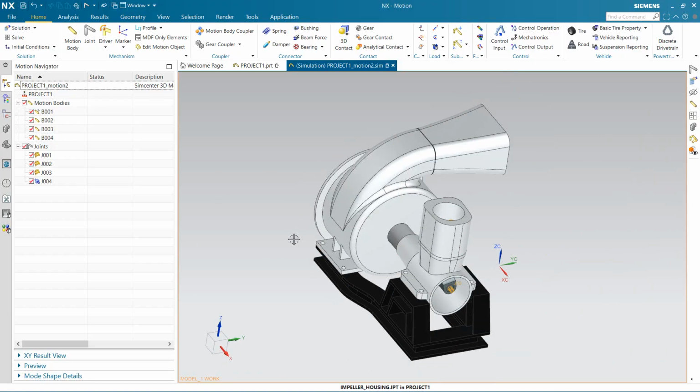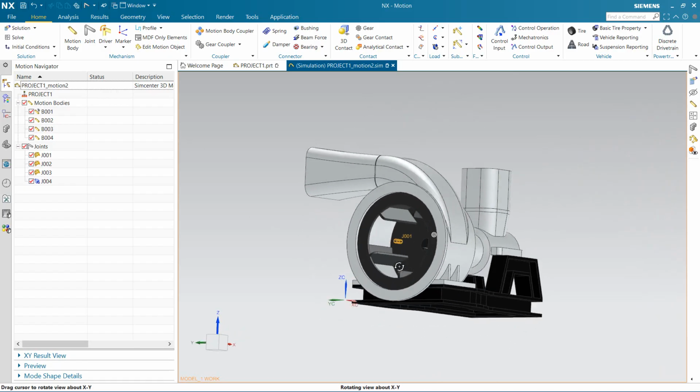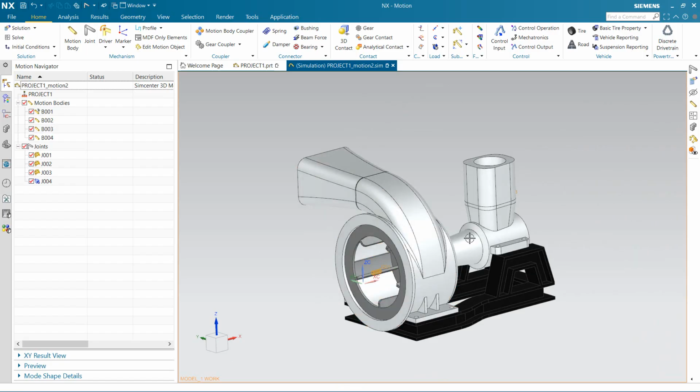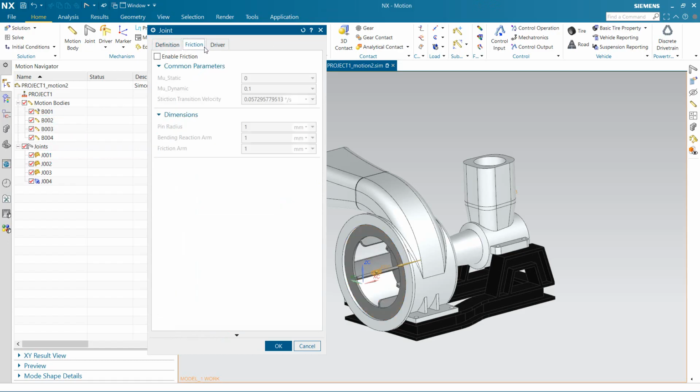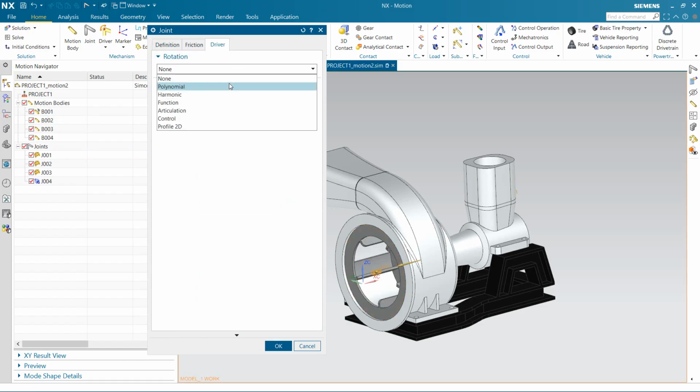Let's show that. That is basically everything. But if I choose to create an animation here, things are not going to work because we don't really have a driver. Even though those things can move compared to each other, there's nothing actually moving them. For example, if you have a car, the wheels can move compared to the car itself, but you didn't run it, so it won't spin as you want. So now you have to choose a driver. I would choose this one as a driver.